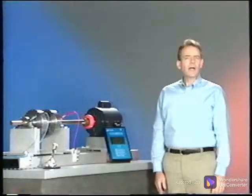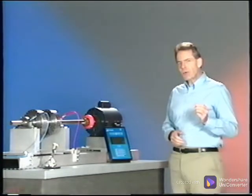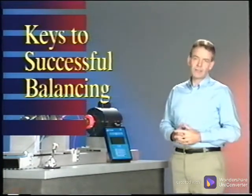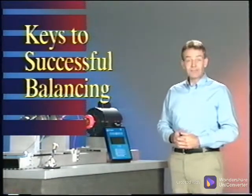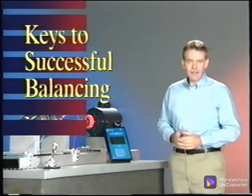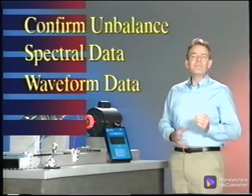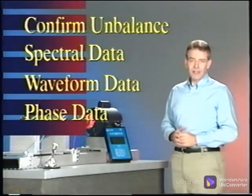Unbalance is one of the leading root causes of machinery failure, and this program unveils the keys to successfully perform single and two-plane balancing on common industrial equipment, such as fans, pumps, and motors, to reduce machinery failure and increase uptime. You will be able to use the tips and techniques presented here to confirm machinery unbalance conditions using spectral and waveform data and phase data to avoid some of the common problems associated with field balancing.